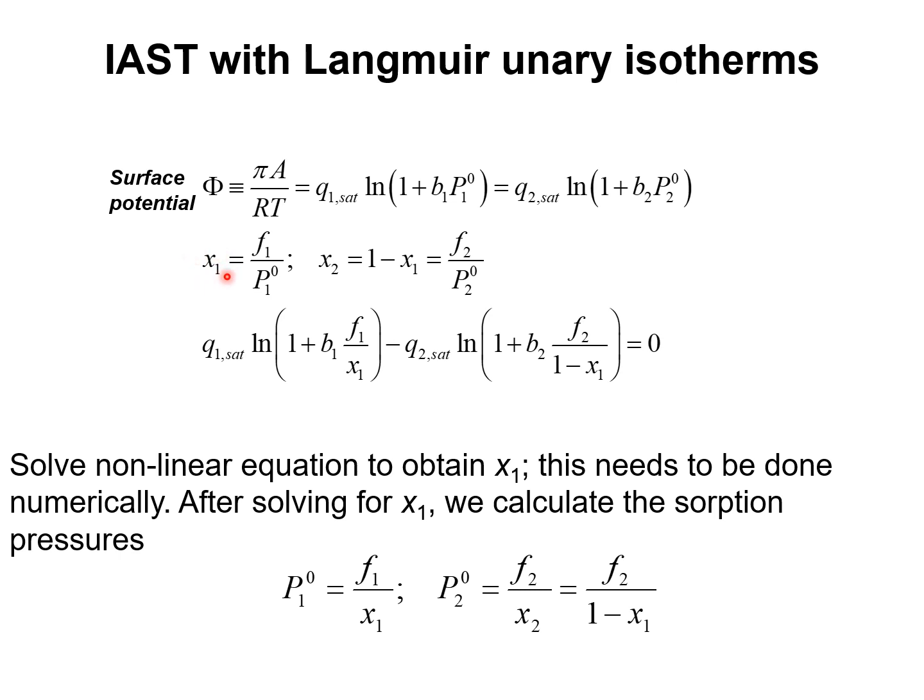We also have the relation between the mole fraction in the adsorbed phase and the sorption pressure for component 1; the mole fraction of 2 in the adsorbed phase, which is equal to 1 minus x1, is related to the sorption pressure for component 2. Inserting these into the expression for the surface potential, we obtain the following relationship.